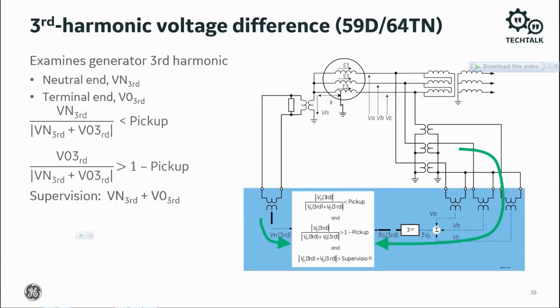For a high impedance grounded machine, choose the neutral resistor such that the power dissipated in the resistor during a single line to ground fault is approximately equal to the reactive power produced by the zero sequence capacitance between the stator winding and the GSU low voltage winding, which is X0C. At the power system frequency, the neutral resistance is equal to X0C divided by 3, and at 3 times the power system frequency, Rn equals X0C.